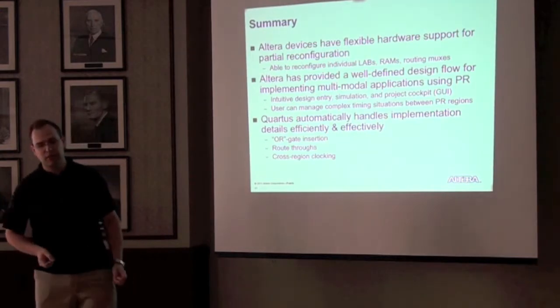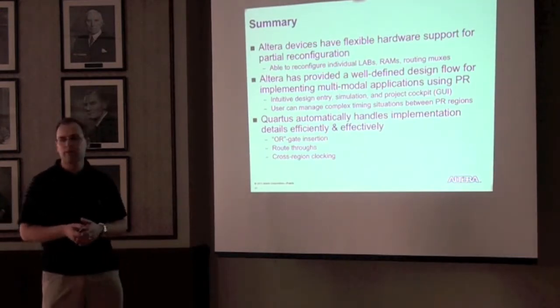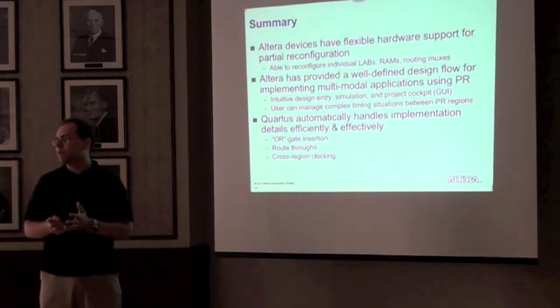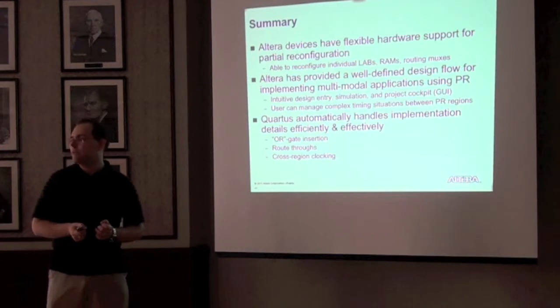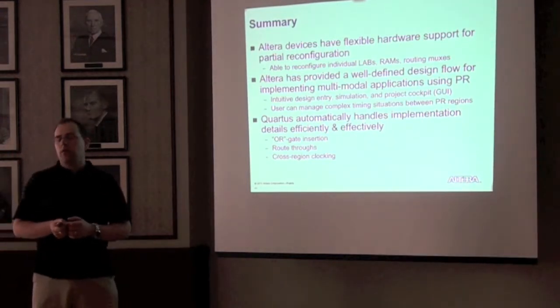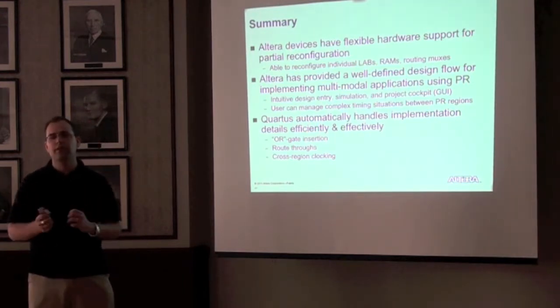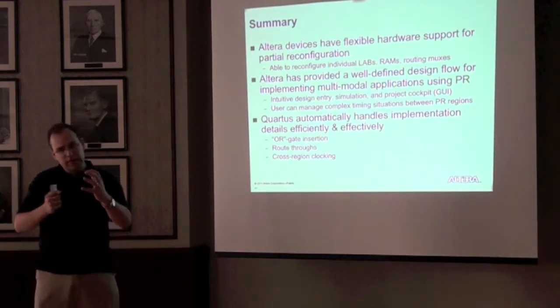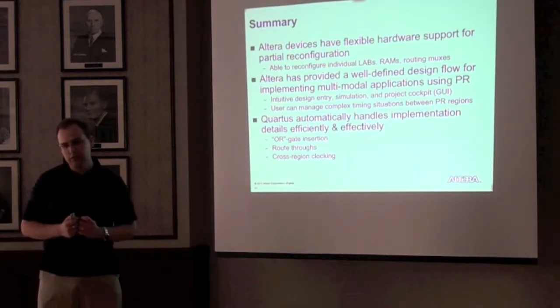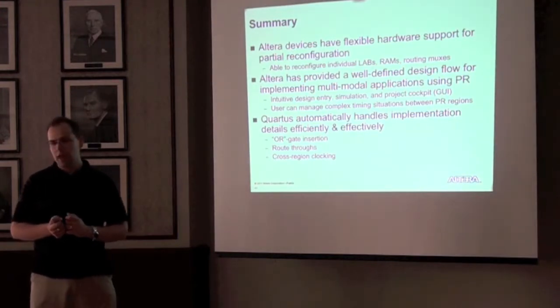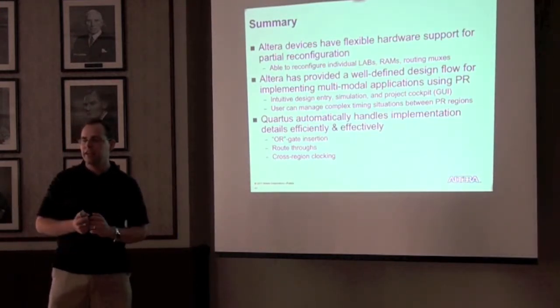So what have I shown here? Altera devices have flexible hardware support for partial reconfiguration. We can reconfigure labs, RAMs, and individual routing muxes, which allows route-throughs to be handled easily. We have a well-defined flow for implementing multimodal applications using PR. So it's intuitive design entry, simulation, and also a wrapper GUI that allows quick access to any individual combination of personas.